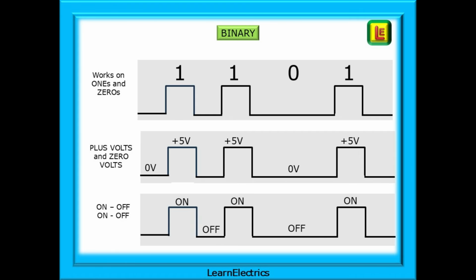Logic gates work on binary inputs and outputs, ones and zeros. They return a logical result from the signals at their inputs. Logic circuits can be clocked so that they all work in synchronization. The ones and zeros are nothing more than the level of the voltage at the inputs and the outputs. 5 volts, for example, being a 1, 0 volts a 0. We will often talk about the signals being on for a 1 or off for a 0.